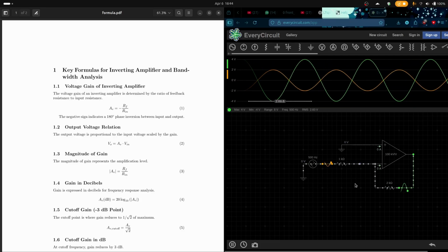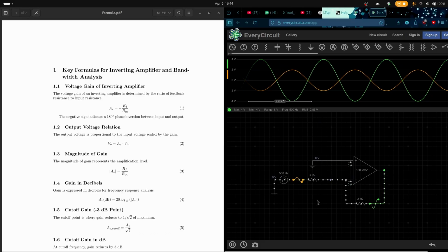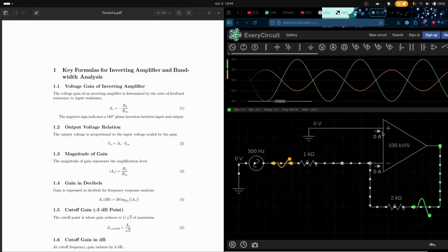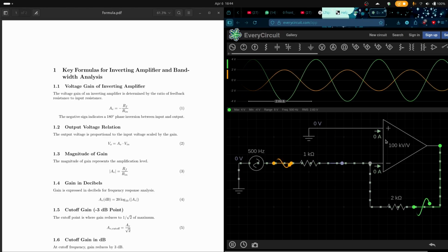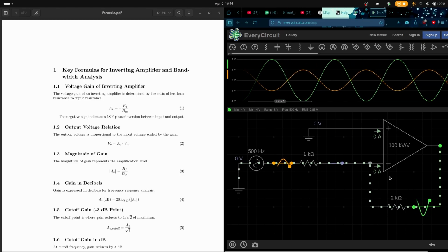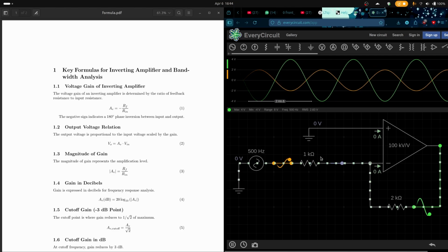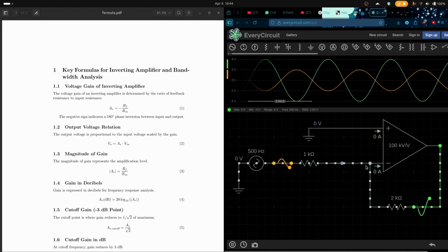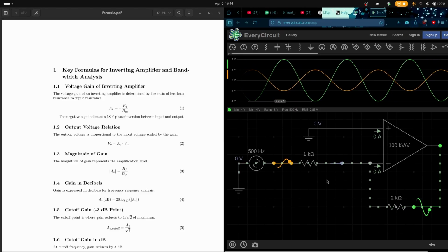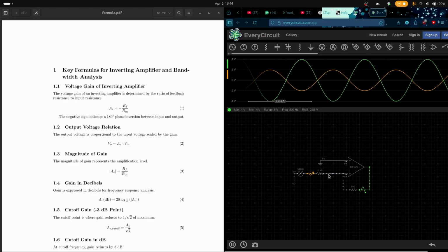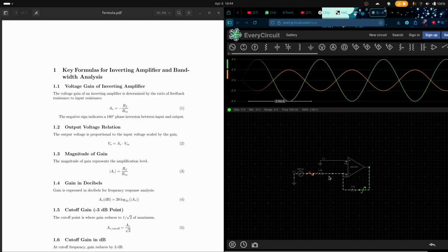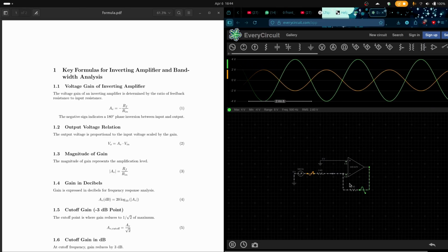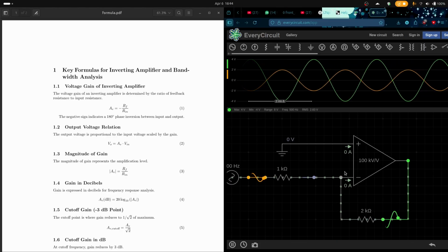If I have to explain with this system right here, you can see that there is no current flowing in the op amp. You can see 0 and 0 at both the terminals, and the whole current is flowing between the feedback loop. This is the inverting feedback configuration. Now, deriving the gain expression, let's break that down and make this circuit feel more logical than voodoo magic.